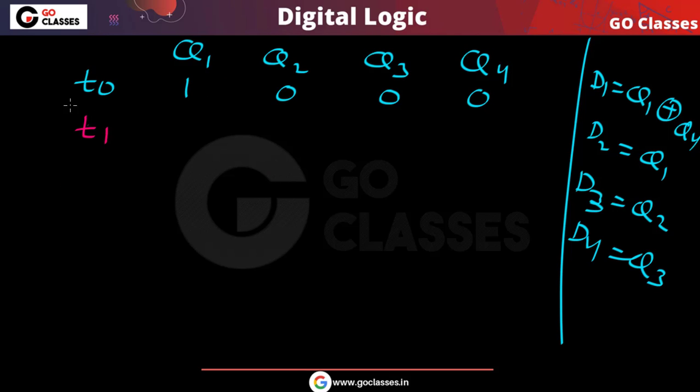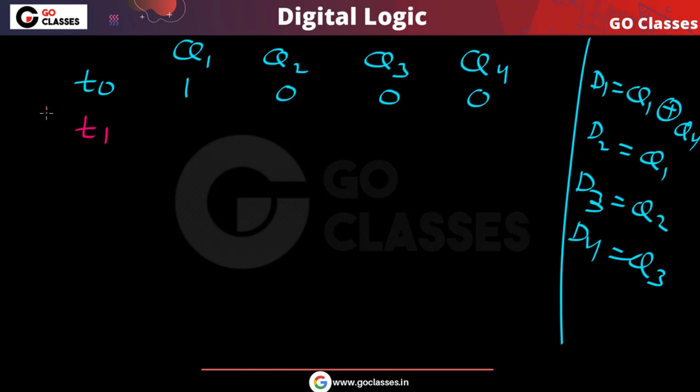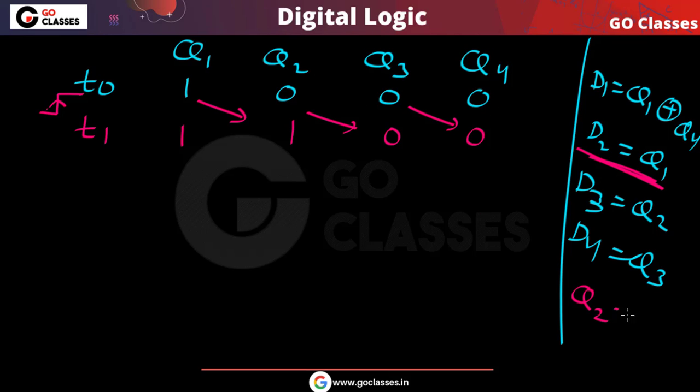After one clock pulse, what will happen? All the flip flops are positive edge triggered, so after one positive edge, this 1 exclusive or 0 is 1. So this will become 1, this 1 will go here, this 0 will go here, and this 0 will go here. This is happening because D2 is equal to Q1, and Q2 is equal to D2.